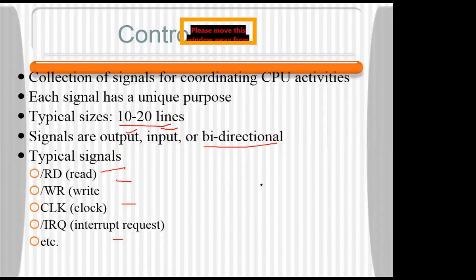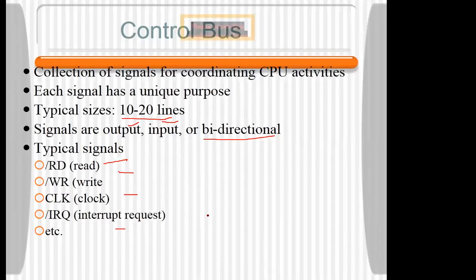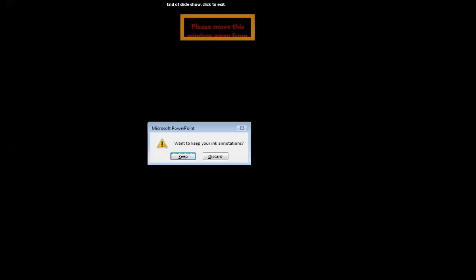That's why I was saying we need a control bus, data bus, and address bus, and that functionality should be there. So we said the data bus is bidirectional, the address bus is unidirectional. Addresses come only from the CPU. Then the control bus is also bidirectional. So basically, that's what we have as for now. And as far as the system bus is concerned, right?